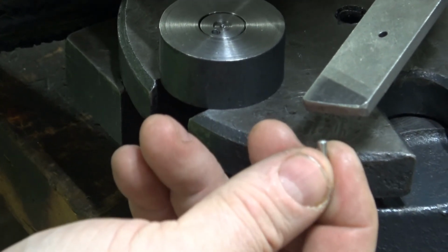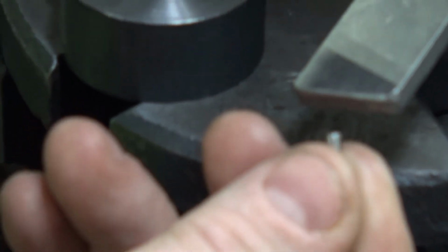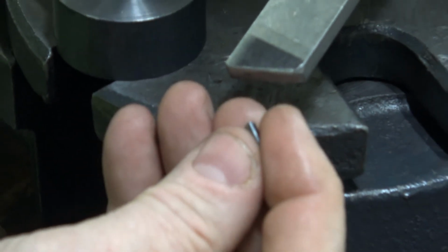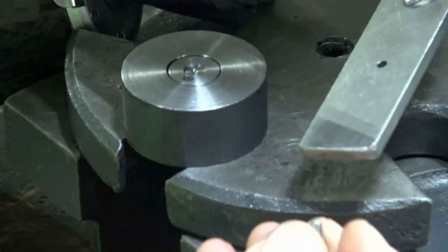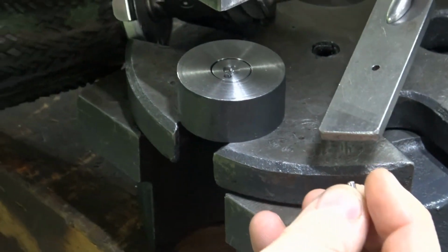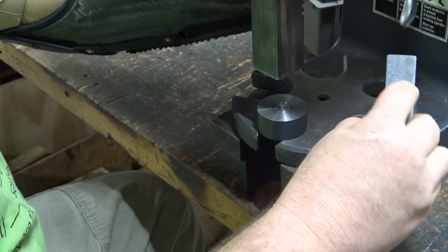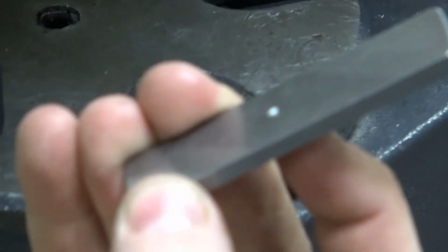So what I like to do is start with the radius side down first. Okay, so that goes down in the hole first, because this chamfer on this pin especially is extremely short, and if it gets tilted just a little bit, it's going to shave material off the side of the inside of that hole. So what we're going to do is take that pin and feed it down through the plate. So you should see that, right? It starts coming out the other side. Once it comes out the other side, we can set it on top, and it's critical that that pin be lined up with the hole.